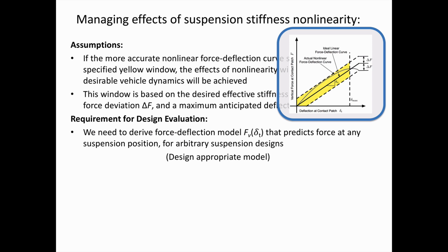It not only needs to accommodate any appropriate level of deflection, it also needs to accommodate changes in physical system design. So if we change the geometry of the suspension linkage, then we need a model that can accurately predict the force deflection curve given those changes in design.